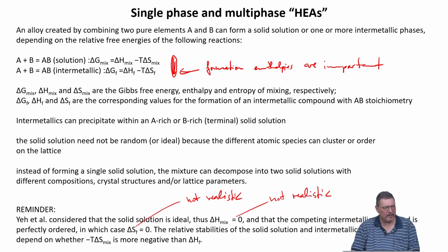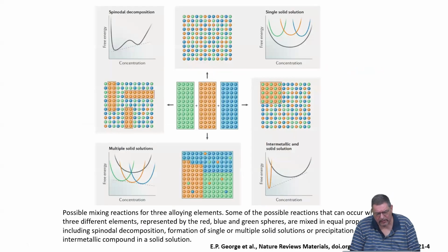So a good system which approaches the mixing enthalpy to be equal to 0 for binaries is copper nickel. But still there, we have a slight positive enthalpy of mixing, and at low temperatures, it has now been confirmed that there is a miscibility gap. So spinodal decomposition will occur when we go to sufficiently low temperatures and wait then for very, very long times. So again, this is difficult, and this is what can happen, right?